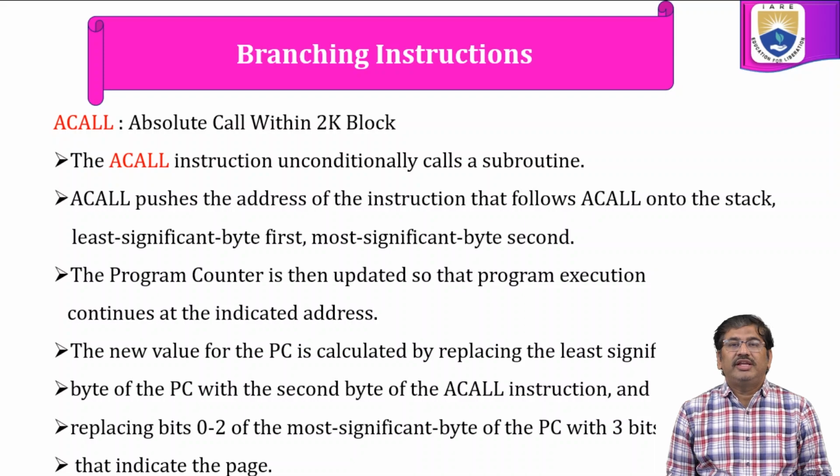The program counter is then updated so that the program execution continues with the indicated address, which is nothing but the address of the subroutine.